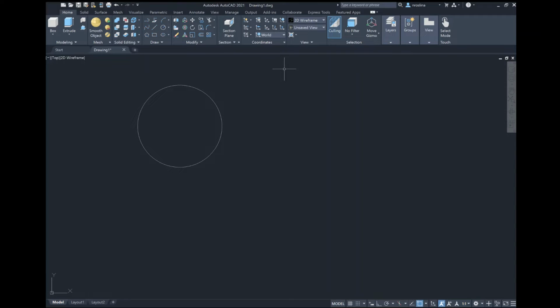So for our next circle, circle number 2, we type in CIRCLE again and enter. And then it will ask to specify the center point of the circle. We know that the center point that we need is 270, 210. I press enter, and then again it will ask me to specify the radius of the circle. We want a radius of 50, so I type 50 and enter.